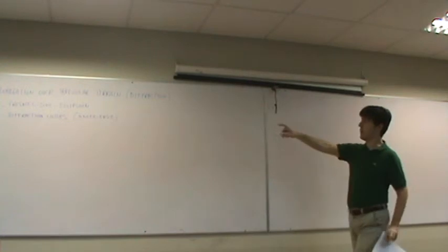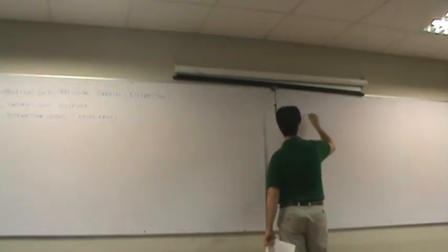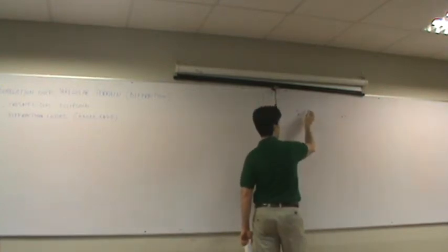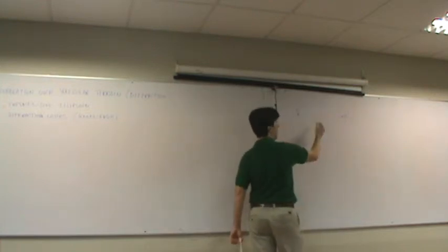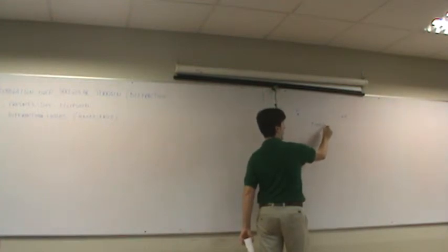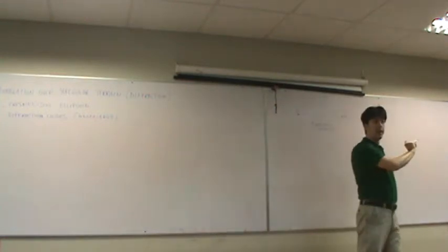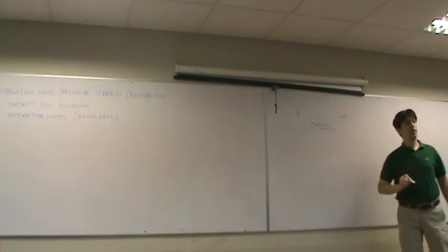Okay, the first concept, the Fresnel ellipsoid, is that when you want to connect point A to point B, you must leave a region around the link free from obstacles, if possible. Not just the direct geometrical link, not just the direct path, but an area around the link.